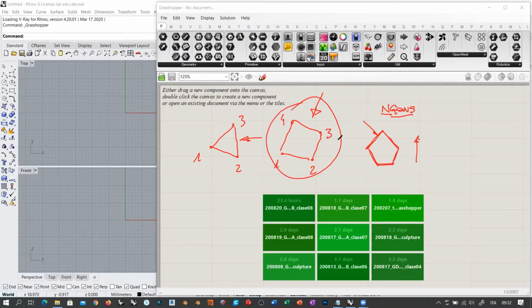But for us, it's probably irrelevant. For example, if you want to do a high resolution rendering with a very highly detailed model, then you can easily use triangles. There is no problem with that. We are going to work with quads in our workflow, not because we are going to animate our objects, but because we need this kind of topology. The particular thing about quad topology is that it has two orientations. When you have a quad, you can flow through this quad horizontally and vertically.